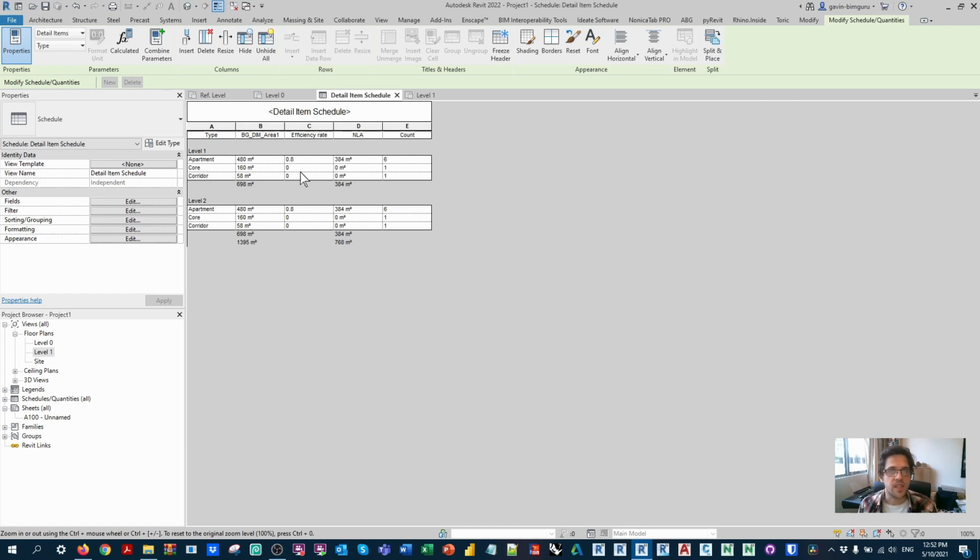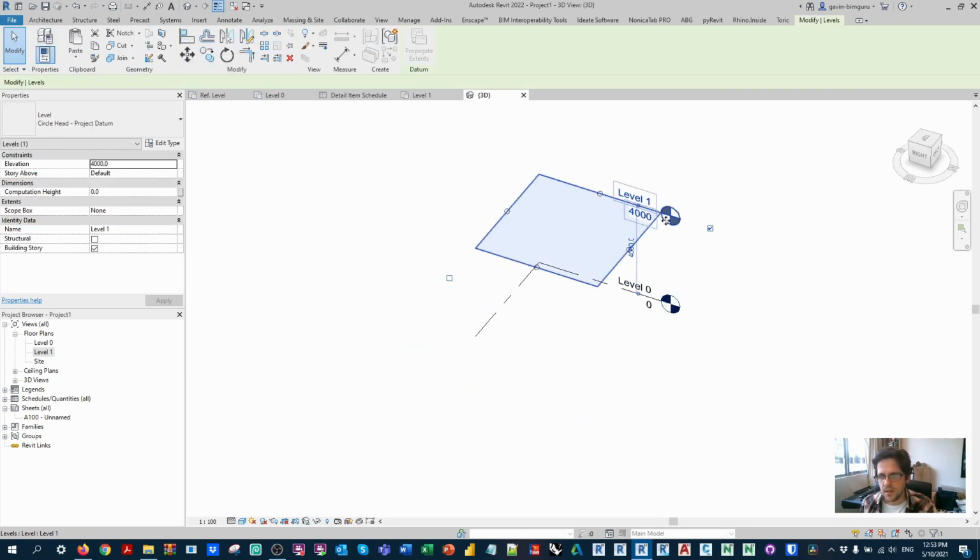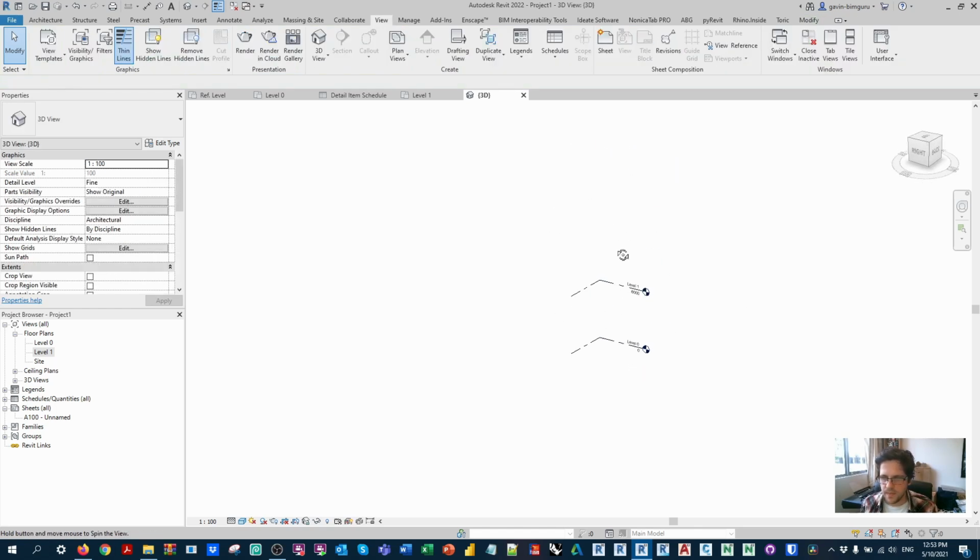So this technique is really applicable to nearly any other workflow I'm going to show you. I might show you in the context of maybe one other workflow we use, but we're going to use about 2 or 3 other solutions here to generate space planning solutions. So what I'm also going to show you quickly is massing. So in this case, what I'm going to do is just delete, I'll keep level 1, but I'll put it up to maybe 6 meters for a podium floor.